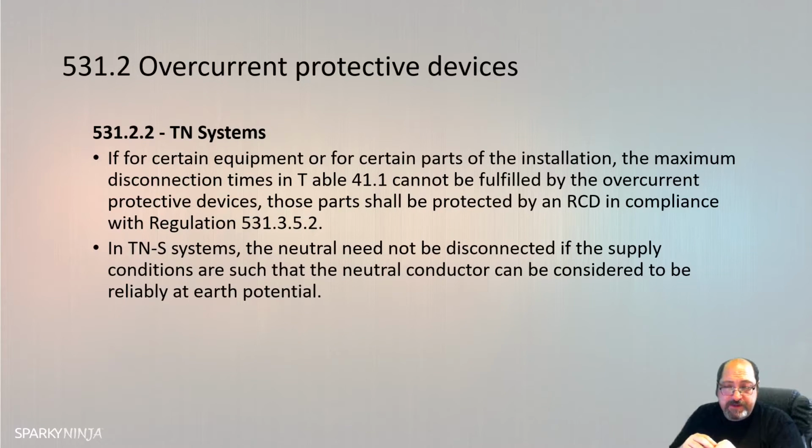If it was a TT system, there's a high impedance there. And we would always, as we said on the previous video, have a multipole, 4-pole isolation in the 3-phase TT system.